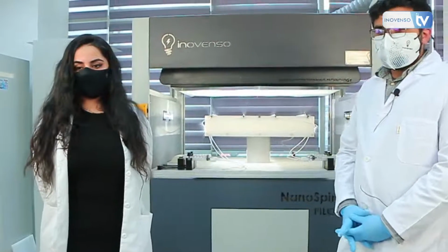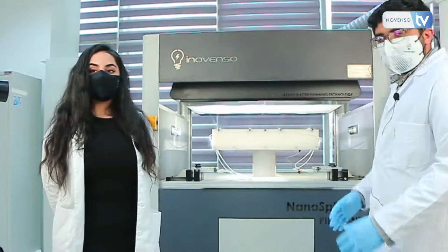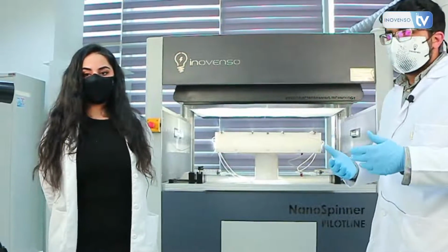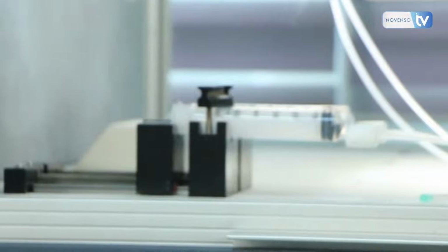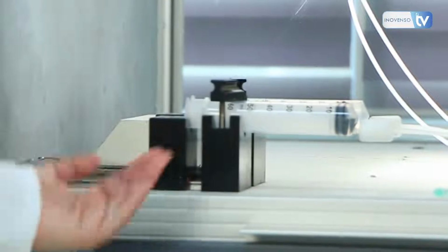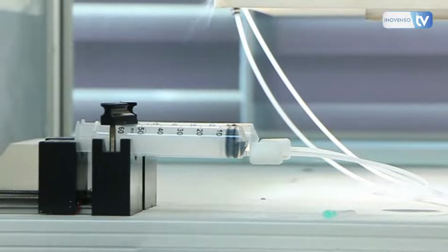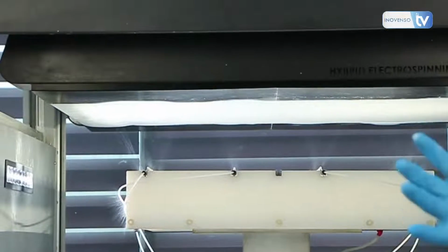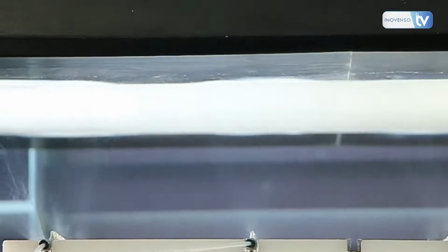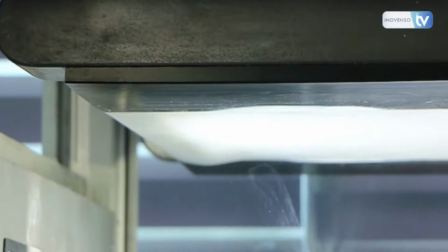Another question is, do you need to stop when the syringe is empty, or is there autofilling? For syringes, based on the flow rate, you occasionally need to change them when they're running out. As you can see right now, they're running out a bit. In a while, they'll need to be replaced or refilled to continue production. But in the case of using the peristaltic pump, as I mentioned earlier, there's non-stop production because we have a large tank of chemicals at the bottom of the machine that just pushes it all the way up. So it does not require as frequent a change as the syringe pumps.